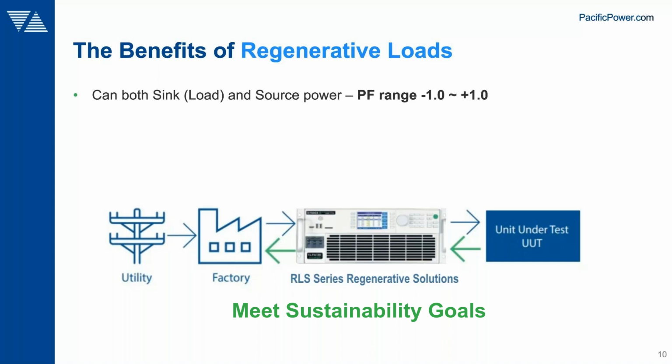So they can cover the entire programmable power factor range for your load conditions. One of the biggest advantages, of course, is the energy savings and thus the cost savings that you obtain. Typically, regenerative electronic loads have the ability to cycle a little over 90% of the power back to the utility. So you're recouping a lot of energy by using regenerative loads.